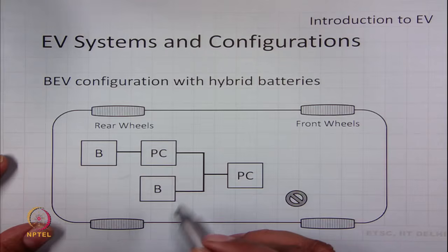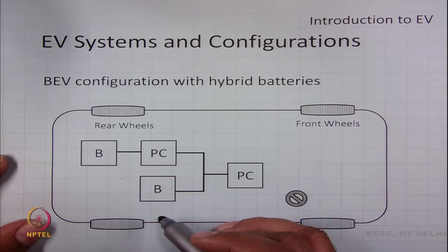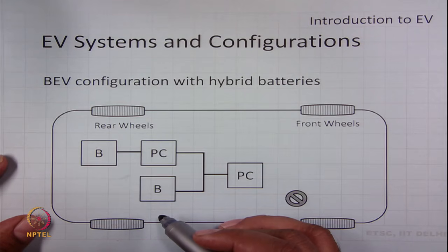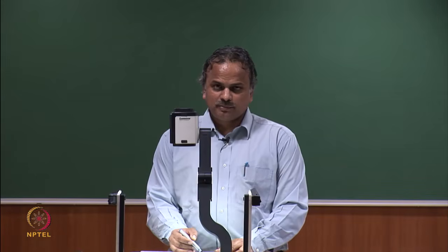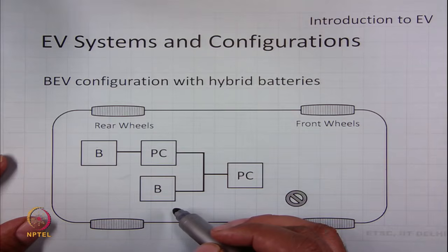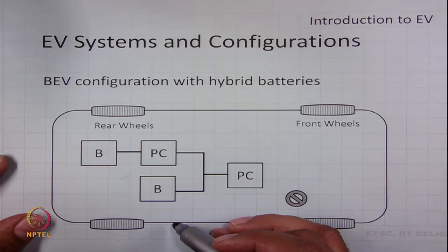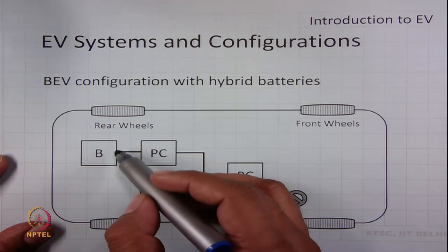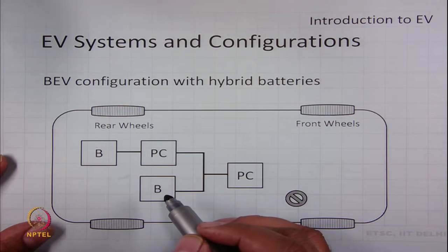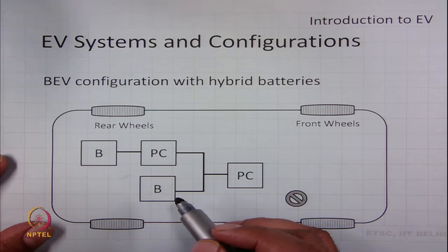Now, because we have two battery systems, it is possible to decouple the requirement of high specific energy and high specific power. So, one battery can support high specific power and one battery can support high specific energy, which is feasible. Secondly, it also gives the option for mechanical batteries such as zinc air, aluminum air and upcoming lithium air.